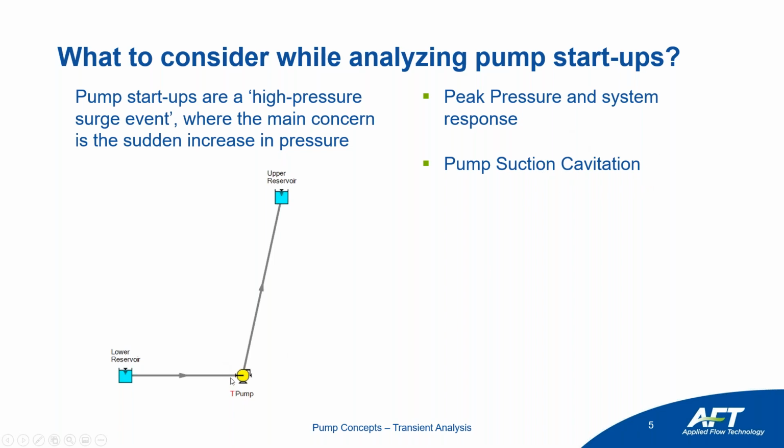It could cavitate within the pipe. It could reduce to such a point where it no longer meets that net positive suction head requirement, and it could cavitate inside of the pump. But again, something to be concerned with is we think about the high pressure generated downstream of the pump, but it'll also cause a localized low pressure at this point, which will similarly travel upstream until that can balance out and approach a new steady state. So we'll see how we can examine this phenomenon as well in the software, and then we'll actually have a case where we do cause cavitation at that point.